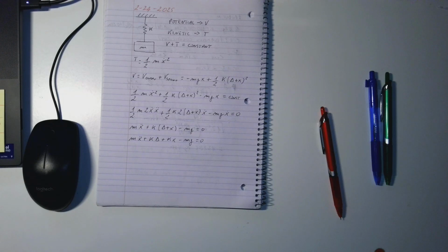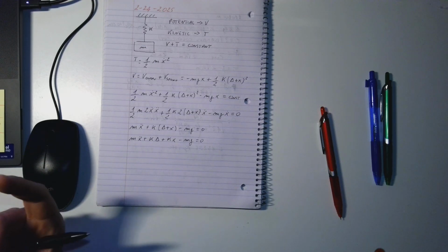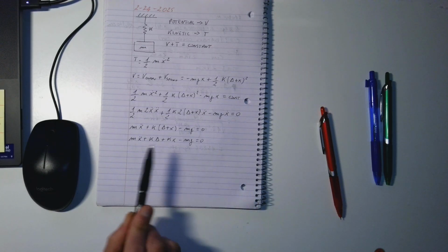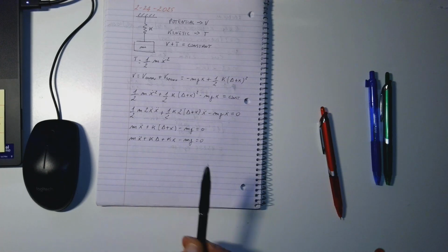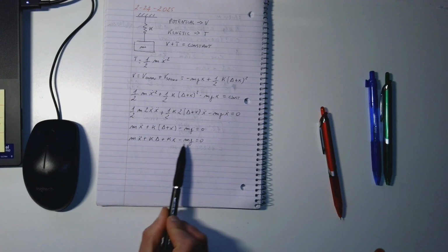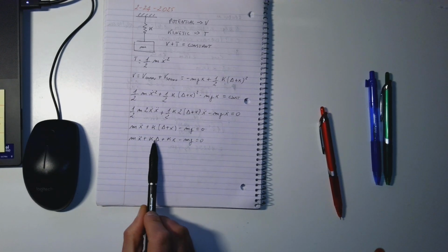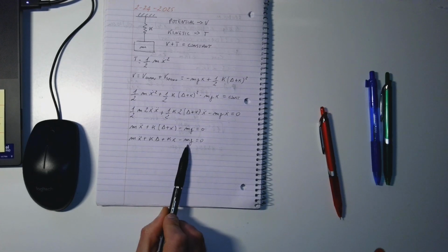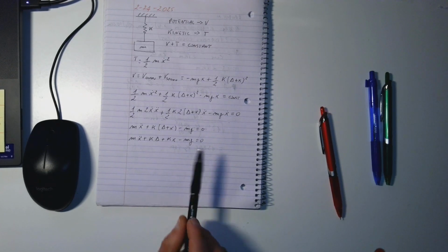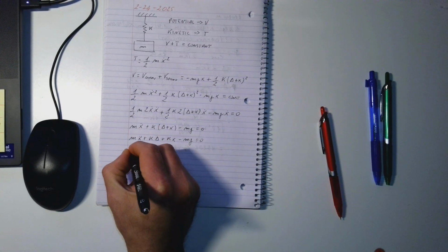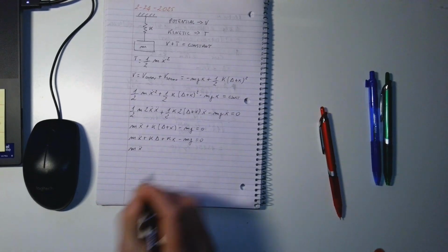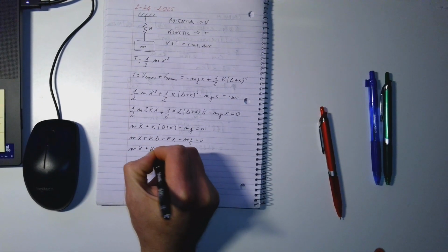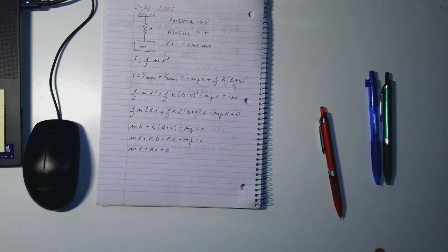The force of the spring is pulling the mass up. At some point, these 2 forces must be in equilibrium, which means that if we look at this expression, we will have k delta is equal to mg, which means these 2 terms can be removed, so we can further simplify our equation. So what we obtain is m x double dot plus kx equal to 0.